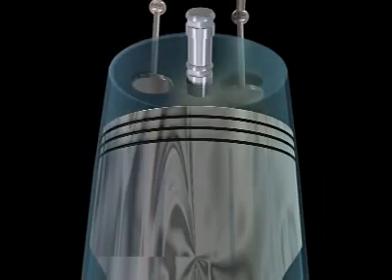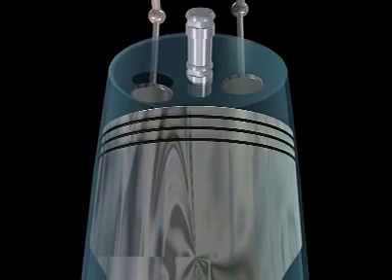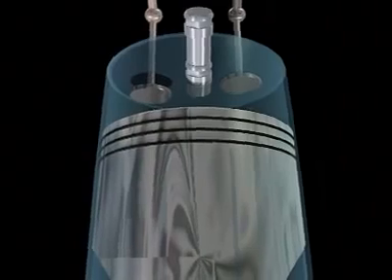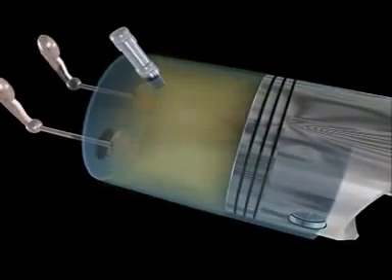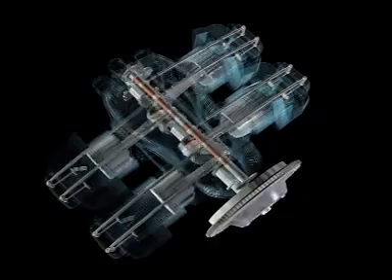When the piston reaches the top of its movement, the exhaust valve closes, followed closely by the inlet valve opening once more. The piston then continues back down to draw fresh fuel and air into the cylinder, and the cycle repeats. This cycle happens continually as the engine runs, drawing fuel and air into the engine, compressing it, burning it,